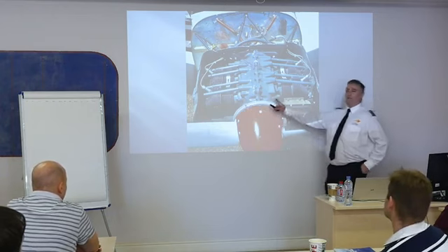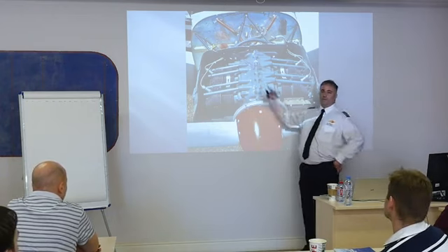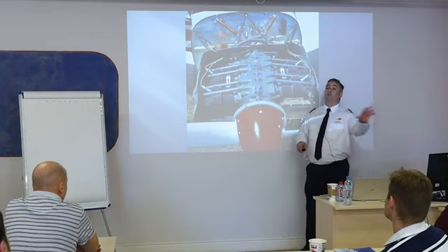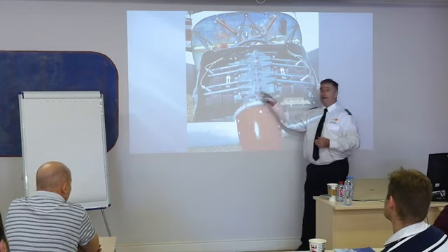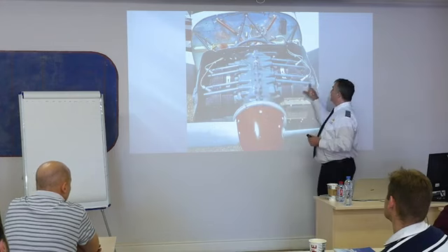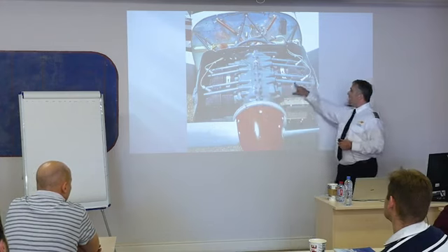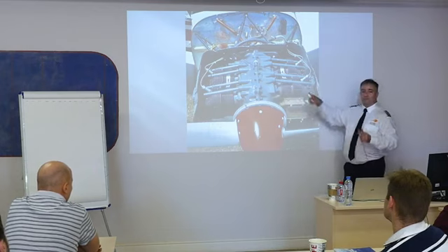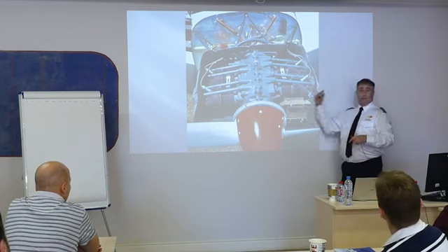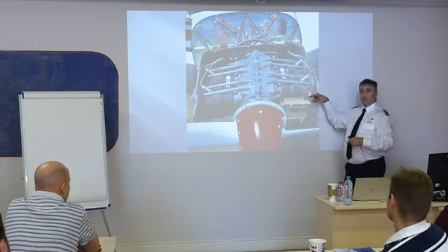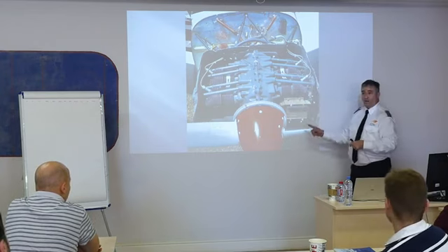Now, inside the crankcase, there's a thing called a camshaft. Forget I ever said that because they will never mention that in any of the books. But there's a camshaft that goes through here, has lobes on it, and these lobes push a rod out to the valves. And the valves open and close and either allow air to come in through the induction system or escape through the exhaust.